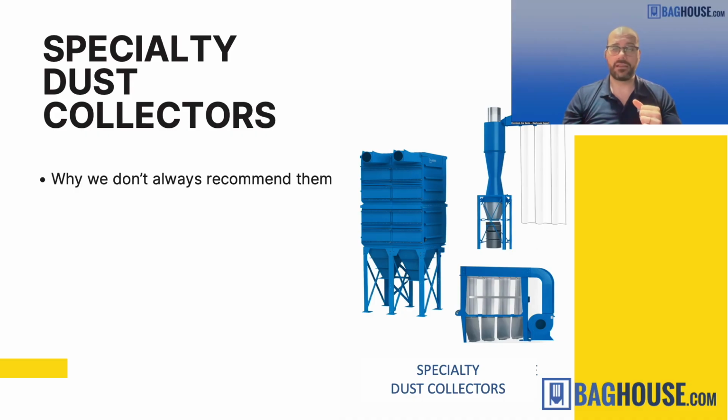Now, the reason we want to be careful with these, modern day regulations for environmental, but mainly for fire and combustible dust safety. These collectors are not as safe in most applications. If there is a spark or a fire, you cannot have any extra kind of protection on these systems, and they will combust, and they will be full of material because they hold the material in the bags instead of discharging it like the other baghouses. So they can pose a safety hazard.